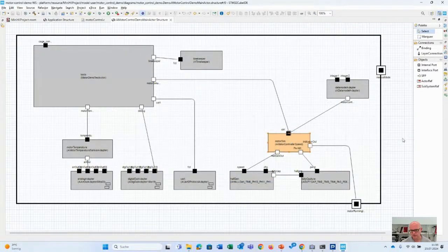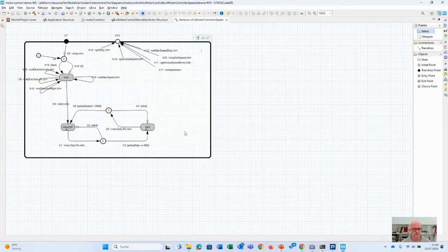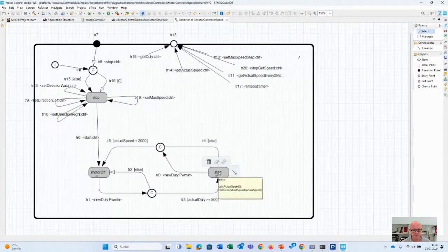here I have a motor simulation. So on top of the IOs, I have the simulations. Motor temperature is straightforward. Celsius converted into an analog output, 3.305 volt. The motor simulator is, of course, a little bit more complex than a temperature simulation because it's closed loop. So in this case, it's a state machine.